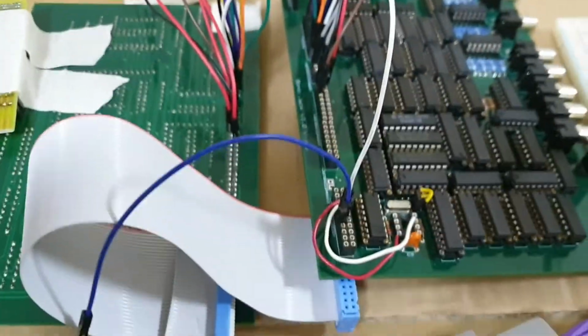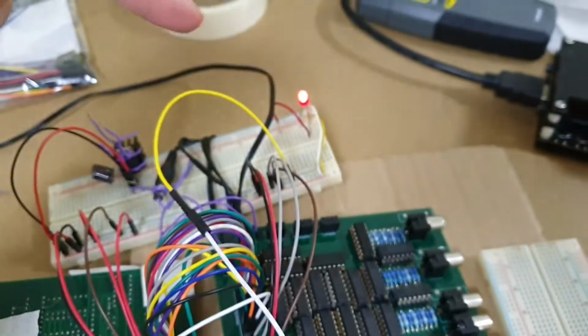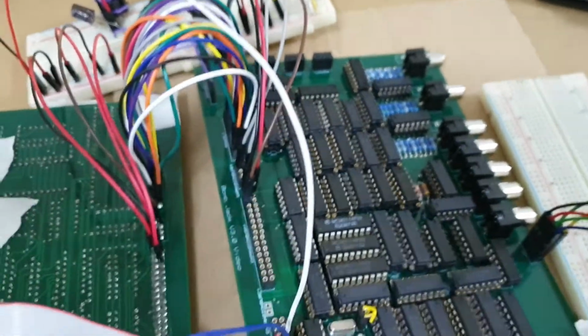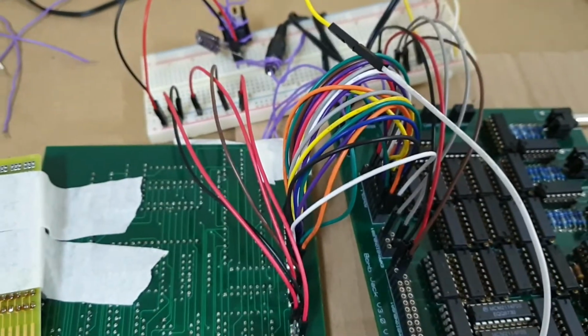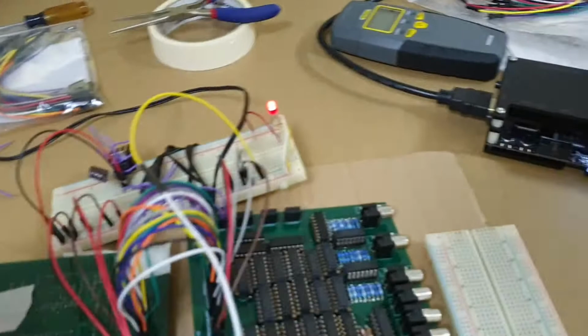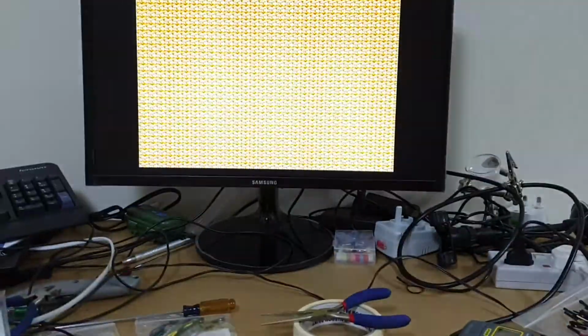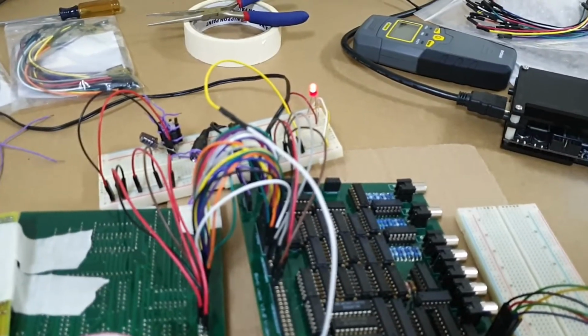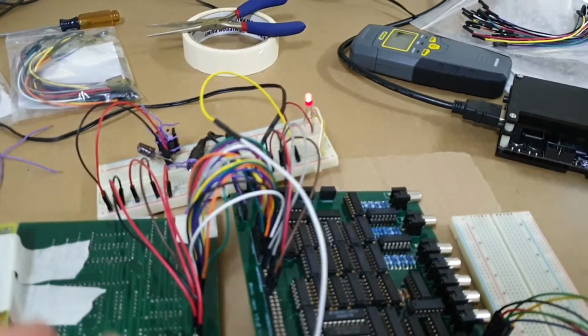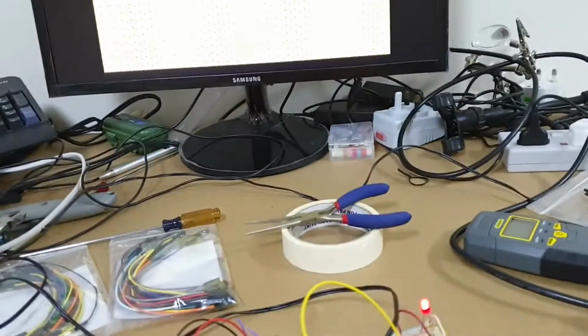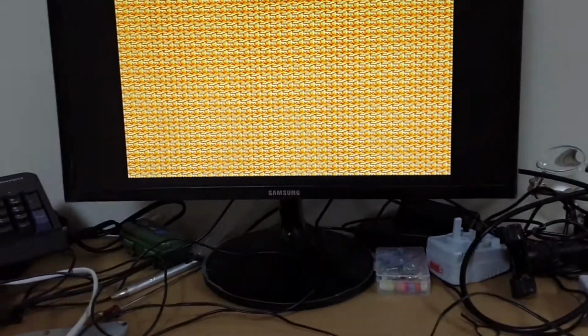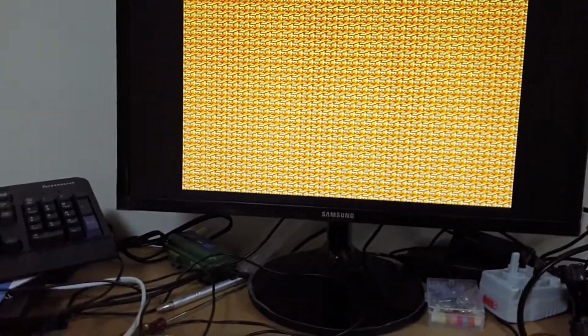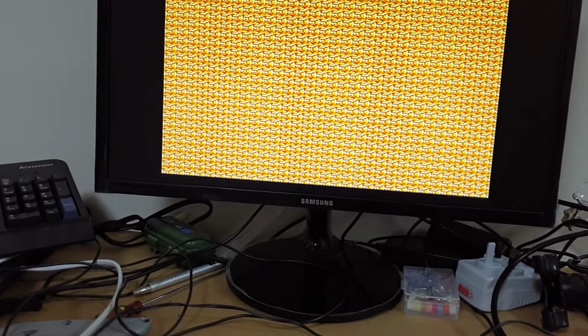So what I'm actually doing is that this long wire here is tying low. I think it's the border Y, yeah, because I can see now that I've got a taller picture, which is exactly as I'd expect. Now, I noticed an interesting effect on the screen as I was connecting up this border Y: it was producing some flickering, alternating vertical lines as I was connecting it up. And I think this is really a good indicator of the kind of electrical interference that these longer wires are picking up as I touch the wire.